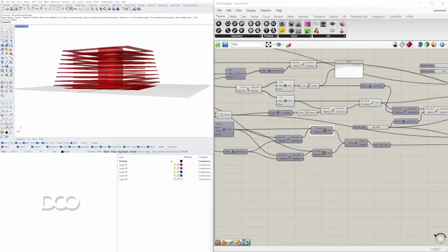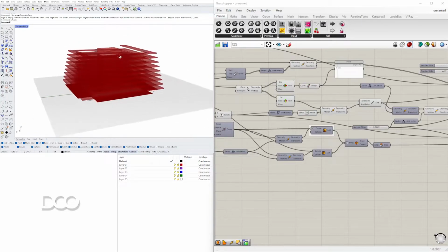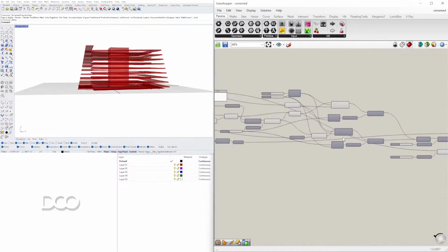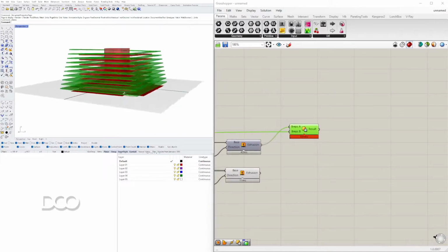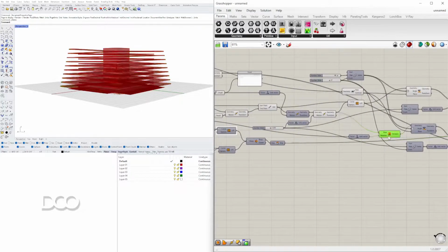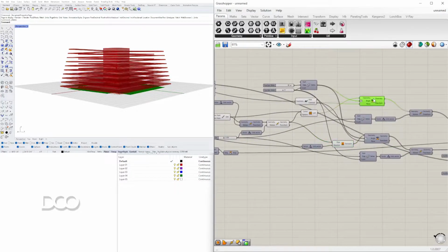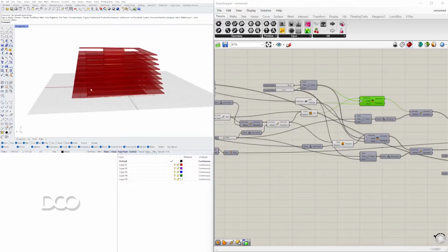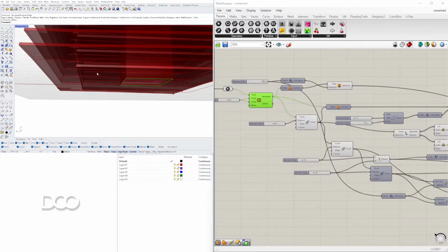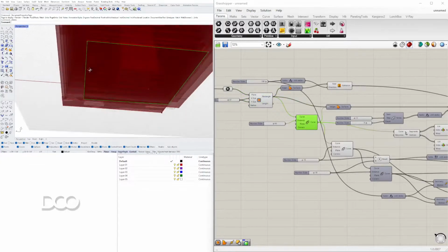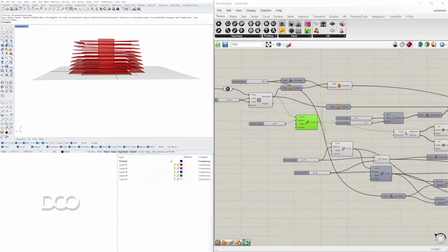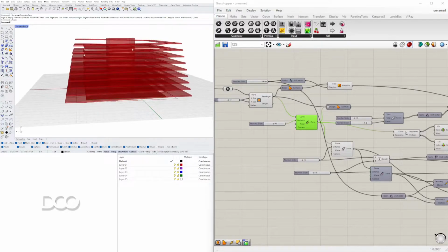Now, what I'll do is let's focus on creating what we talked about. But let's also notice that we are previewing some stuff that we don't need to look at, which is this. Okay, so now let's create the walls. To create the walls, we need to go all the way back to this base curve, offset it to the inside, and extrude it to the same height as the walls.